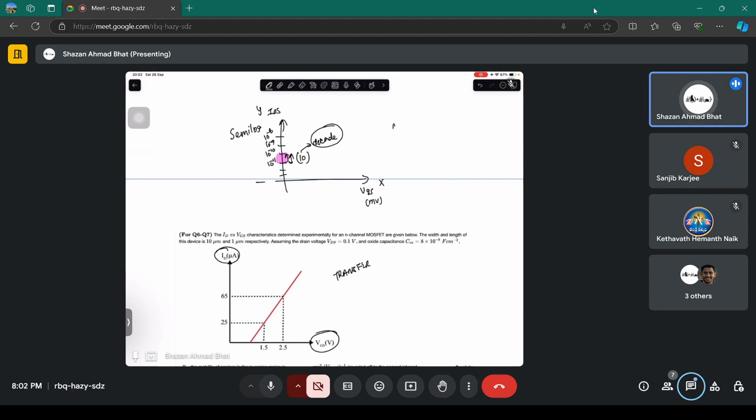That is how the units of millivolts per decade come about. Per decade means per factor of 10. It is suitable for calculation, as well as for showing large changes, because a change of a factor of 10 on a linear plot would be huge and you would have to draw it on a very large scale. That's why, whenever you have such huge changes, you draw it on a log scale.